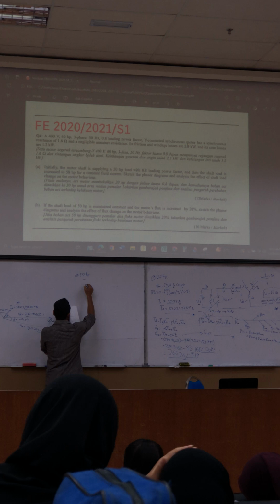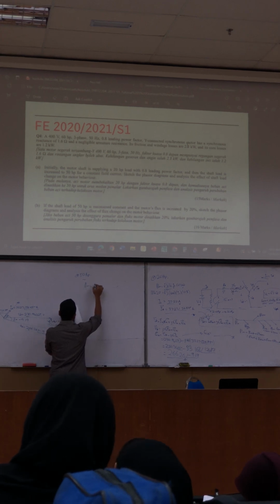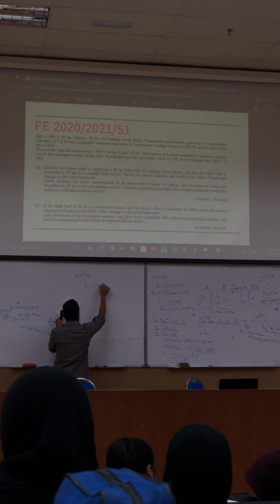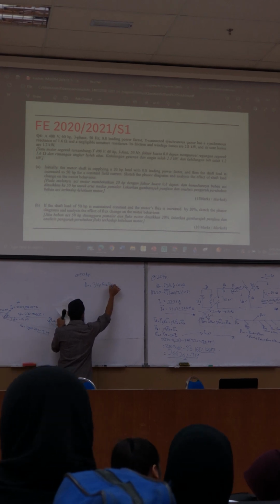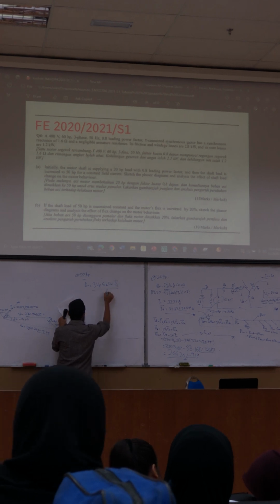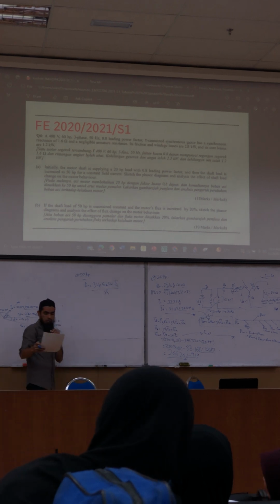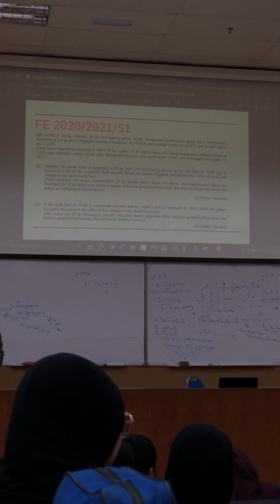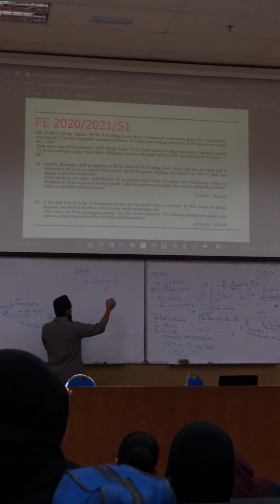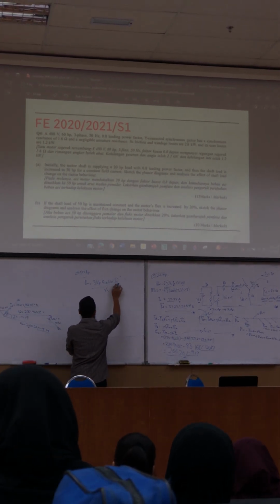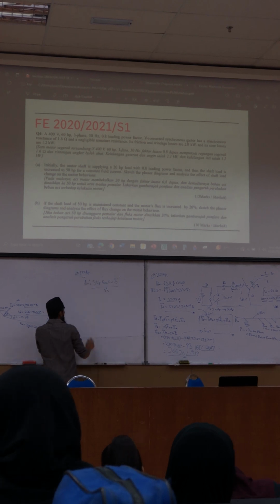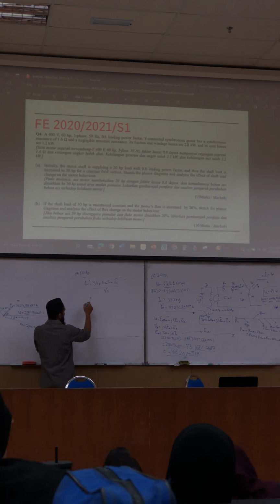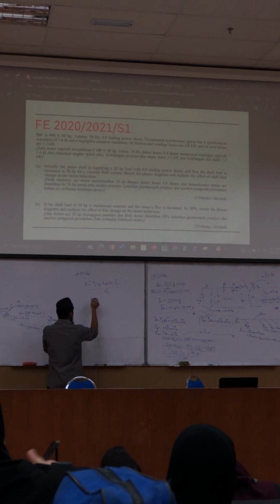We have to use the formula given, which is PA equals 3 V phase EA sine delta over XS. So this delta is the new delta, delta prime. So this is your new PA. Or you just shift first over here.